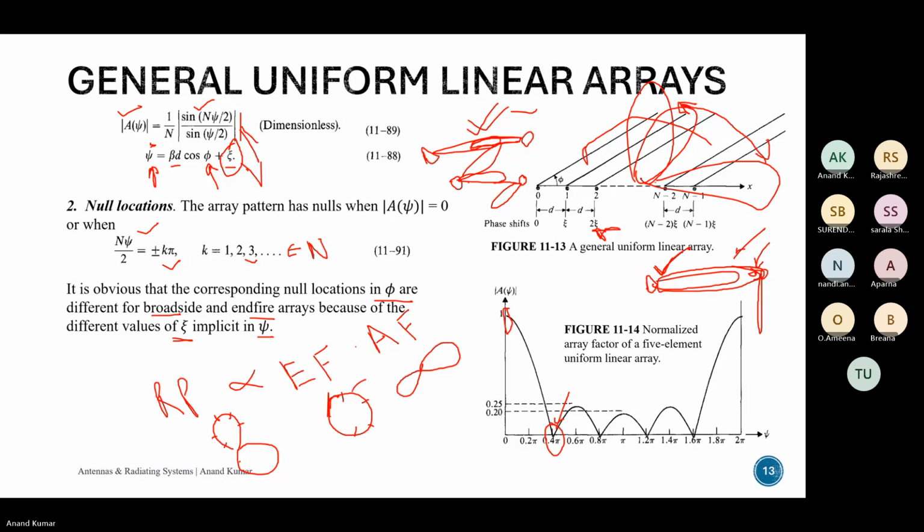So for these two patterns, there is something known as the principle of superposition of patterns. I think maybe we discussed it in the last class. Based on their product is how the final radiation pattern would look. For example, if the element factor had a certain gain over here, but in the array factor this gain is very less, then in this direction the gain would become very less.